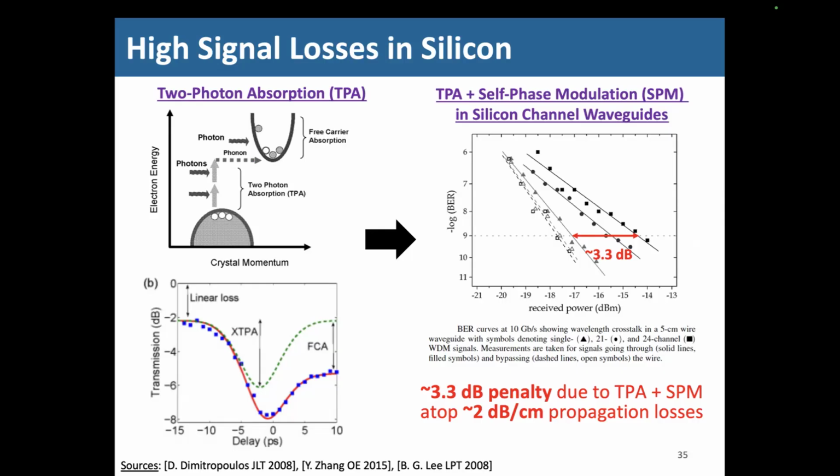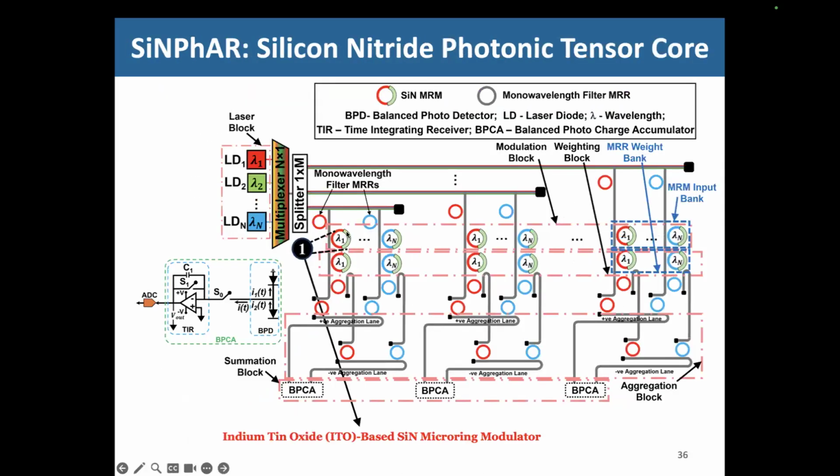And so we basically said, if we have silicon nitride and we try to create a tensor core out of that, how do we achieve that? We thought, okay, if the waveguides are silicon nitride, then it might help to actually have an active silicon nitride modulator and a weighting device as well. Silicon nitride material is not active, but maybe you can have heterogeneous integration of active materials on the cladding. So you can have everything on the silicon nitride platform, sort of, right?